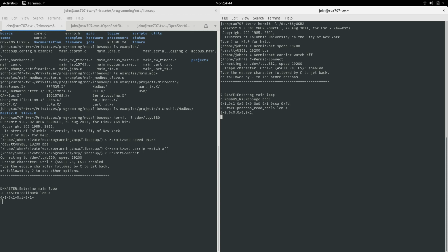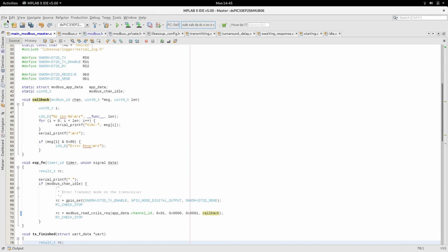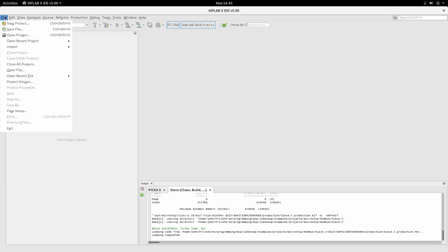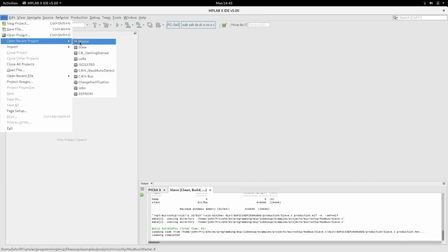Now when the slave reads this message, it's going to check the CRC and strip it off if it's valid. If it's received a good message, then it's fine. It then is going to check the target address, and if this is not for my node, it's just going to ignore it. So our API callback will never be called. So if this is for another node, just ignore it. If it is for this node, then it sends it up to our slave callback.